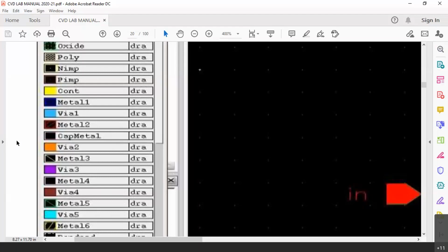If we can make switches which are in the picometer range, then from VLSI to ULSI, ultra large scale integration, then to GSI, giga scale integration. That way it will go on. So here in this particular LSW, you can see only 6 metal layers. Whereas in the latest tools, there can be up to 12 metal layers, which means metal layer over metal layer over metal layer.